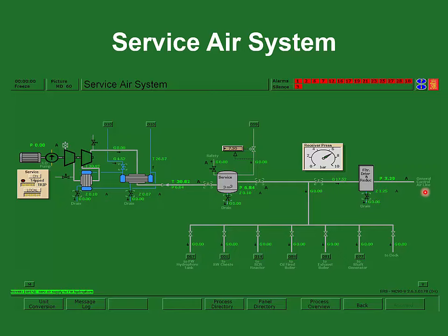The pressure in the receiver is controlled automatically by starting and stopping of the compressor. And these are done with pressure switches. You have a pressure switch to start the unit up and to stop it. Typically, you also have manual control of the compressor, which will bypass the pressure switches and can be used to test a receiver safety valve.